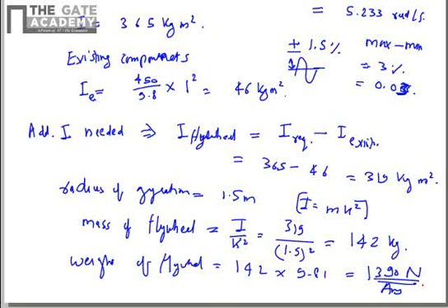In both of the problems that we have considered till now, there is no variation from the supply. The supply is from a motor that is applying constant torque, and the variation is coming from the output, the load. In the first case, the variation came from the punching pressing machine, and in this case, it is coming from the pump. So the fluctuation in load is basically what we will be calculating while doing the calculation of the flywheel. And the same principle applies if the load is constant and the supply is fluctuating, like in the case of an IC engine or steam engine.